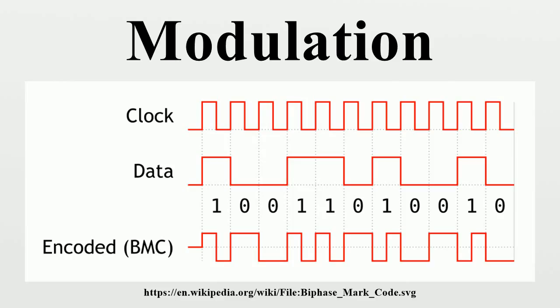Modulator and detector, principles of operation. PSK and ASK, and sometimes also FSK, are often generated and detected using the principle of QAM. The I and Q signals can be combined into a complex-valued signal I plus jQ. The resulting so-called equivalent low-pass signal or equivalent baseband signal is a complex-valued representation of the real-valued modulated physical signal.